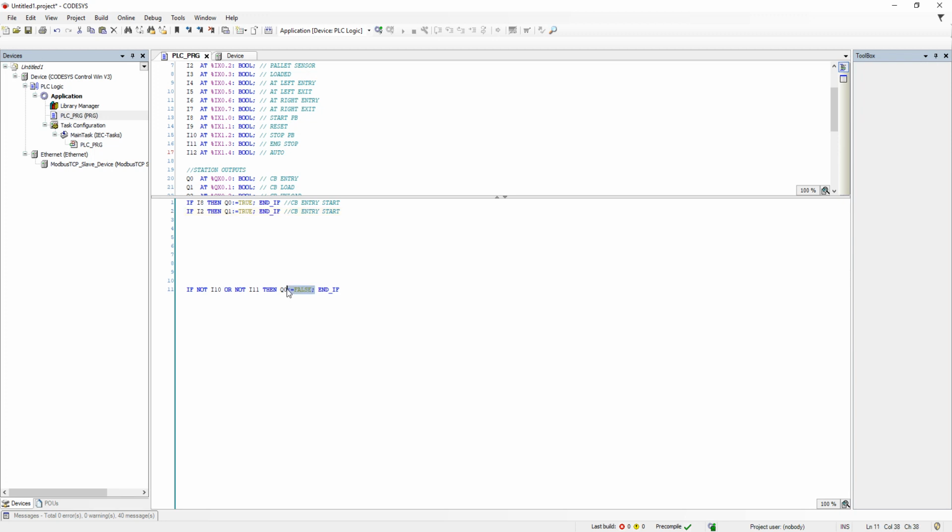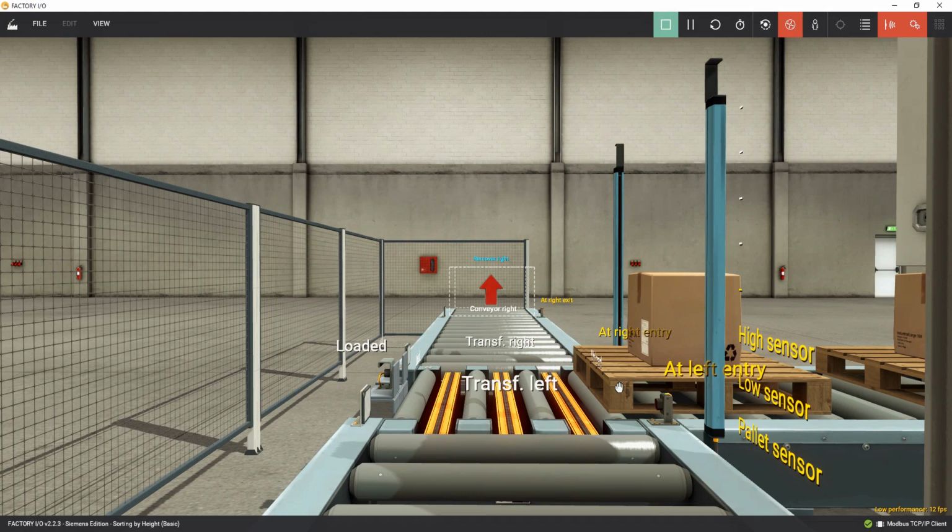So to be safe, always put your conveyor outputs under the stopping functionalities so that you could be able to stop them. So now Q2, because I don't want to act surprised. I know they will have to stop one way or the other. Anything that starts needs to stop. Q6, right? When I2 is on, Q1 is on. It means that this will go forward.